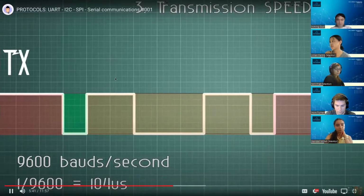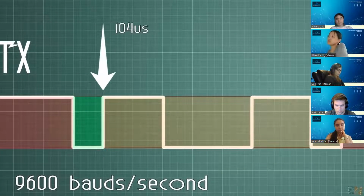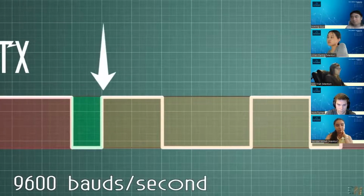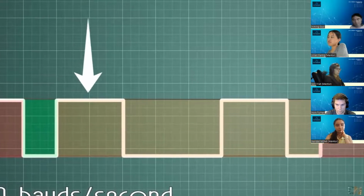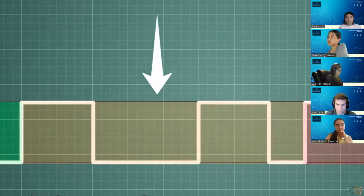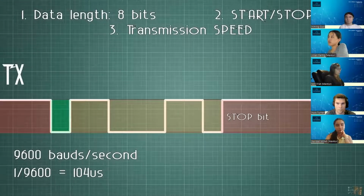So now all the receiver has to do after detecting the start bit is to count time. We count 104 microseconds, and then we are at the beginning of the first input bit. But we don't usually save the value here, because the data is unstable. So we will go in the middle of the bit. So we count 52 microseconds more. And now we save the first bit, and then we count 104 microseconds more and save the second bit, and so on. Once the receiver has all 8 bits, we'll wait for the stop bit, which is represented by a high pulse, and then we can send the received data from the buffer to the rest of the system.